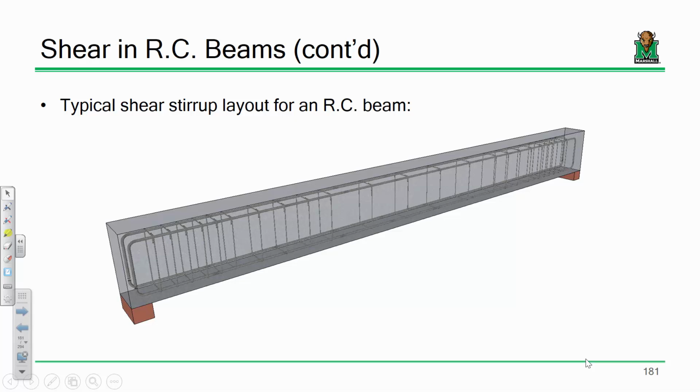So I have tensile reinforcement on the bottom, and I went ahead and threw some compressive reinforcement up top. I don't necessarily always have to have it, but I can count on it if it's there. That compressive reinforcement can not only resist load, but also serves to tie together all of the reinforcement in the beam. The rest of the reinforcement, these little hoop things going on here, are what we call stirrups. And those stirrups are there for a very particular reason. Those stirrups are there to resist the beam's shear forces.